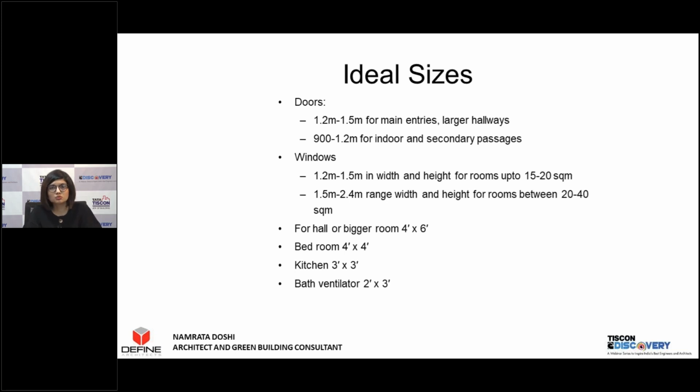That includes people who have hearing disability, vision disability, speech disability. So I think our doors, hallways, main entryways to your homes, to your buildings, need to start catering to these requirements. Usually 1.5 meters or a little higher is preferred in that case.